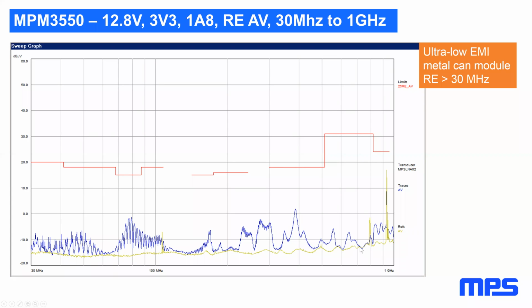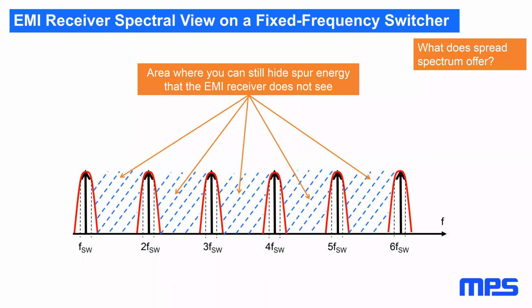The gray one is the noise floor, and I have a GSM base station in my surroundings, so I don't get my system absolutely quiet. However, typically the noise floor of a normal EMI chamber would be in that area, so we are well below what you typically would measure.